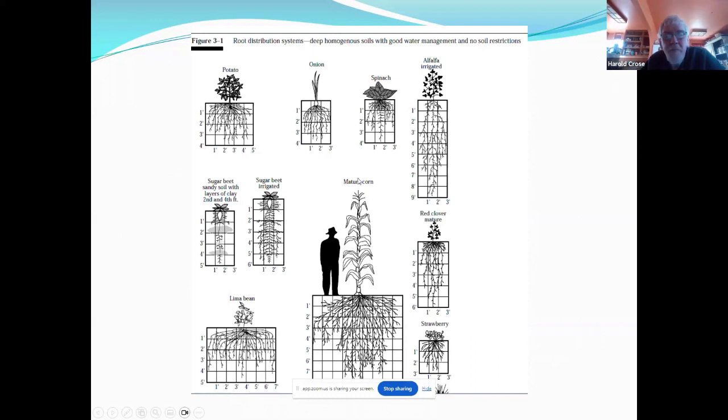The one thing about corn is it's a little bit different critter. You can push water a little bit more on it and its roots penetrate down. And when we were designing systems in the 70s, they were telling us that the root zone on corn was basically 3 feet. And we started digging holes and we found roots down 9 feet on corn.